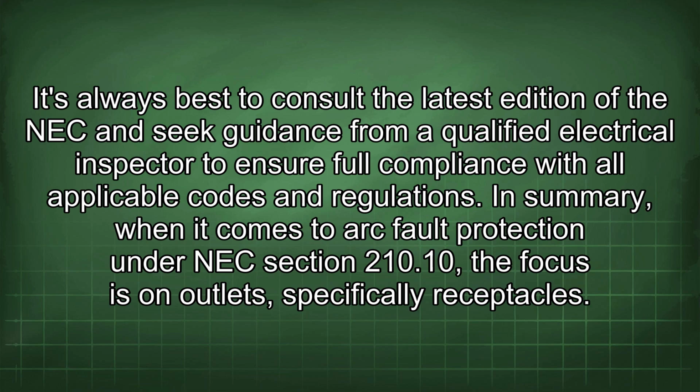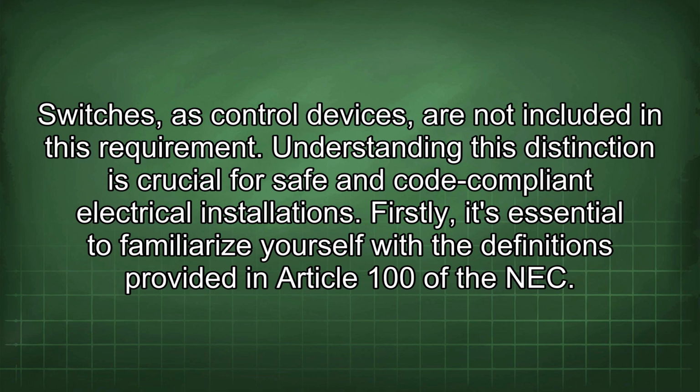In summary, when it comes to arc fault protection under NEC Section 210.10, the focus is on outlets, specifically receptacles. Switches, as control devices, are not included in this requirement. Understanding this distinction is crucial for safe and code-compliant electrical installations.